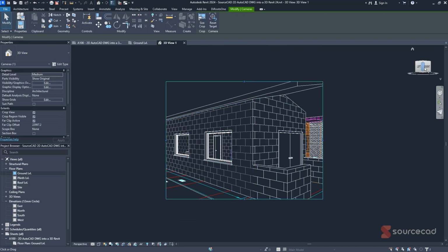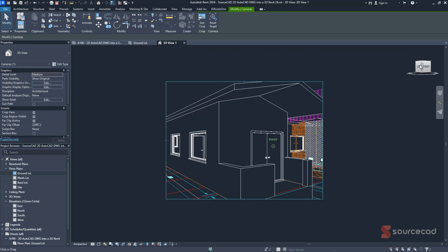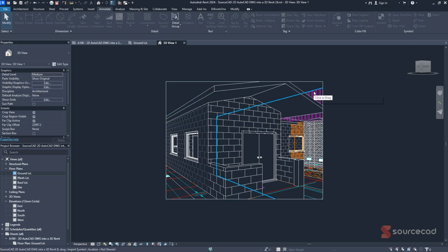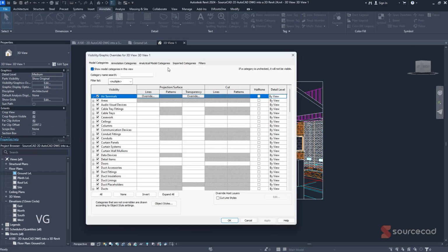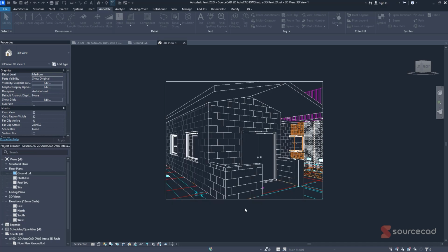And that's the way our structure is looking. Really, really beautiful. So that's the way it looks like. That's the entrance. That's the linked card. So remember, if you don't want to see this, you can just simply hit VG on your keyboard so that you can hide your imported categories, all of them. You can hide everything, click on OK, and just like that, it's all gone.